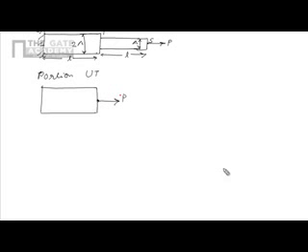So if we take section or portion UT, we isolate the section UT. The P force is acted directly as P, obviously because the force is P, so the reaction must be equal to P. So this is how its free body diagram looks like.